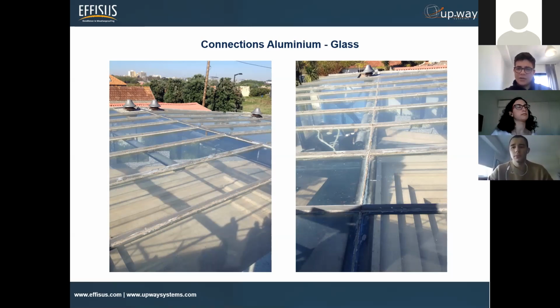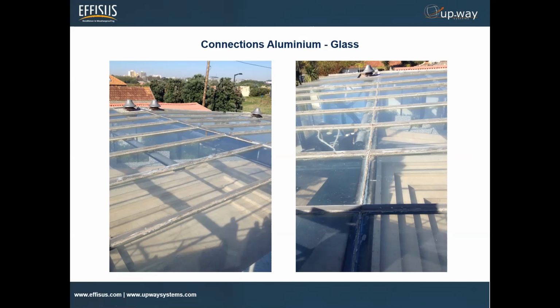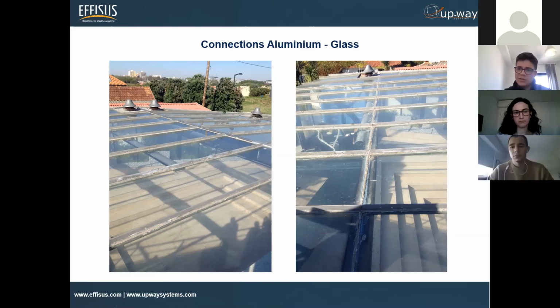In this case, UV resistance. After a couple of months or a couple of years, the material will start to dry out. You see here, it's all dry. So the client tried to remove it, and asks how to repair it and install a material that also allows this type of movement. With a lot of glass, there isn't much movement, but there is some. So we also need to be aware of what type of materials we apply in this situation, because it needs to accommodate movement as well. As we all know, different materials contract and expand in different ways.